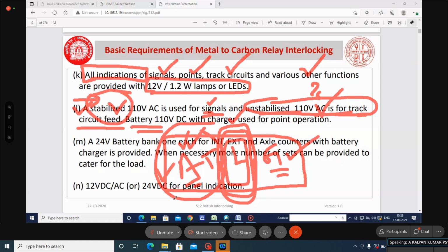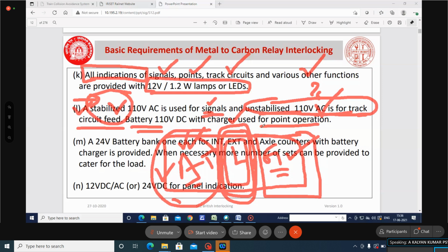If all modes fail, then we need to give the supply for the station through genset. So what is the first thing you are going to ensure while supplying through genset? Suppose that the station load is say some 15 kVA. If I provide a 10 kVA genset, will it work?